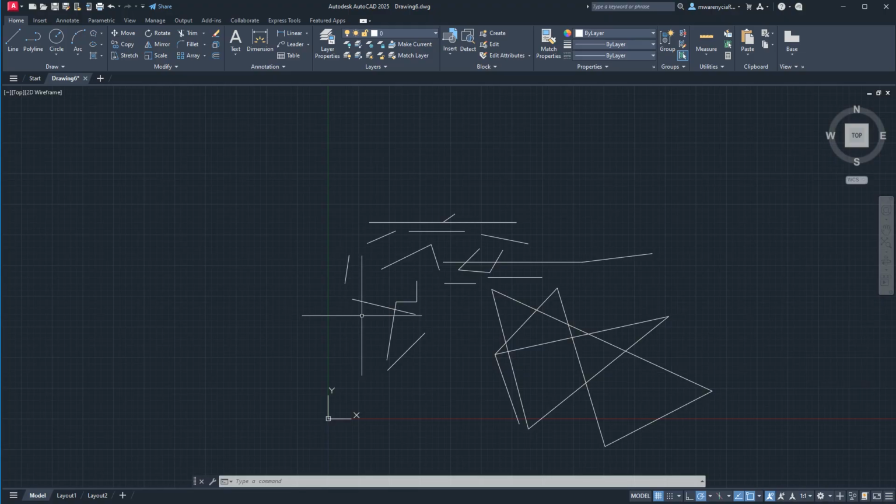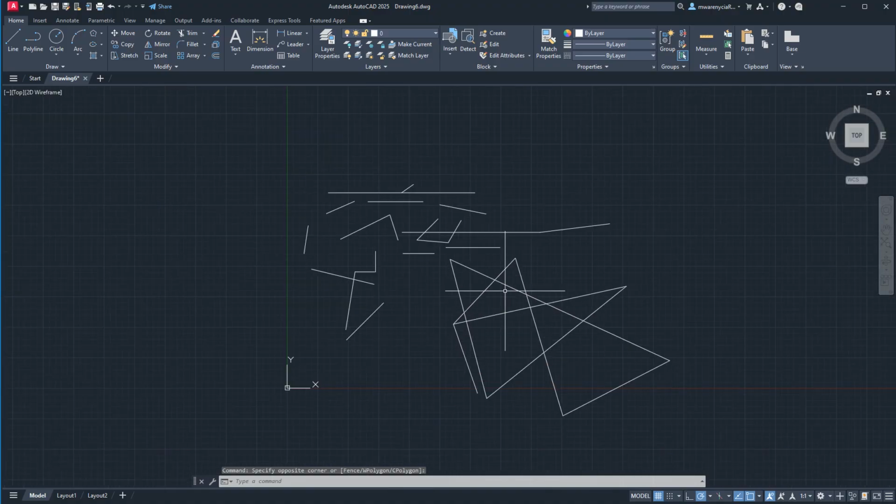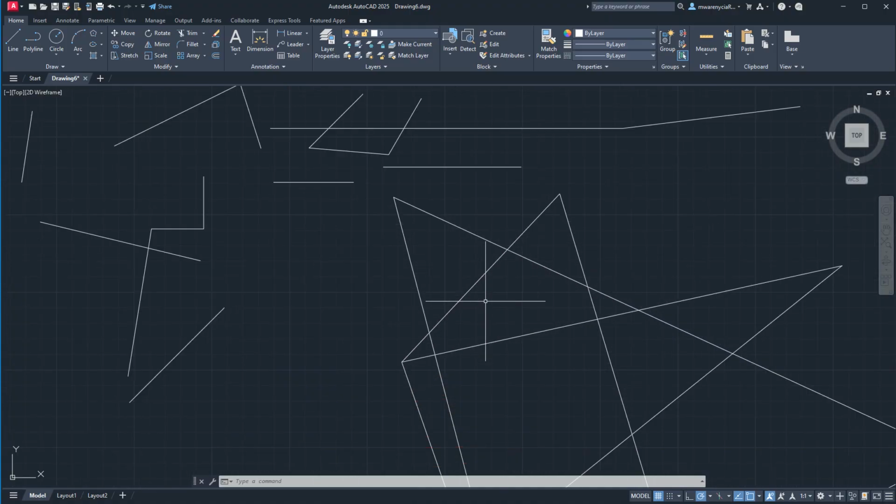Okay, there's undo and what I call the undo trap. So you can see we've got all these things here. What you're used to is undo reverses actions. But AutoCAD considers everything you do to be an action. So me zooming here is an action according to AutoCAD. It's not necessarily logging all of them, but it will take you back to a certain point.